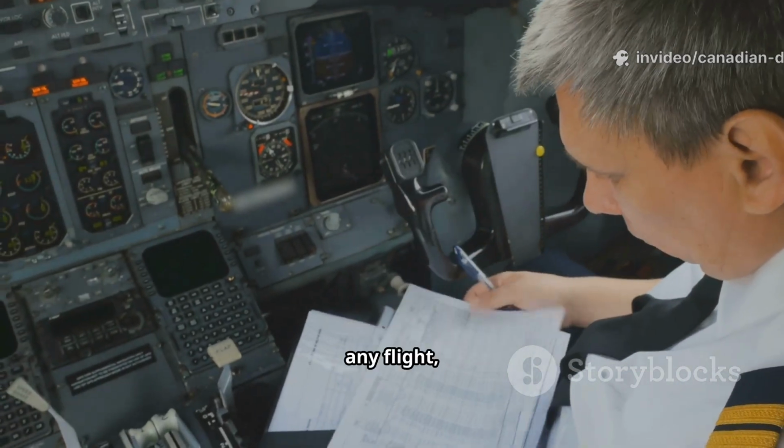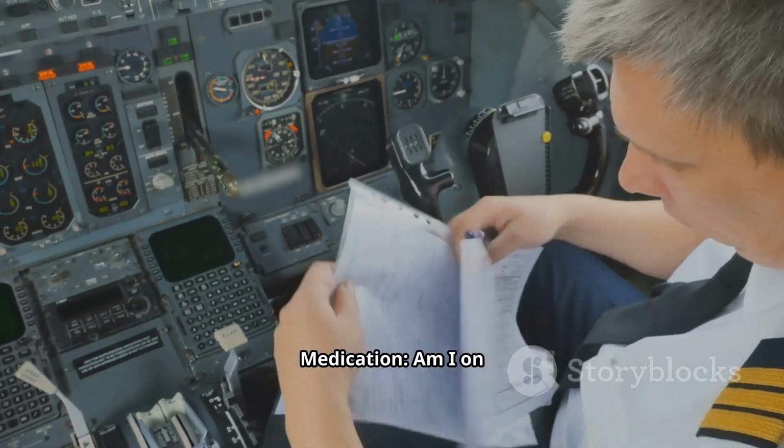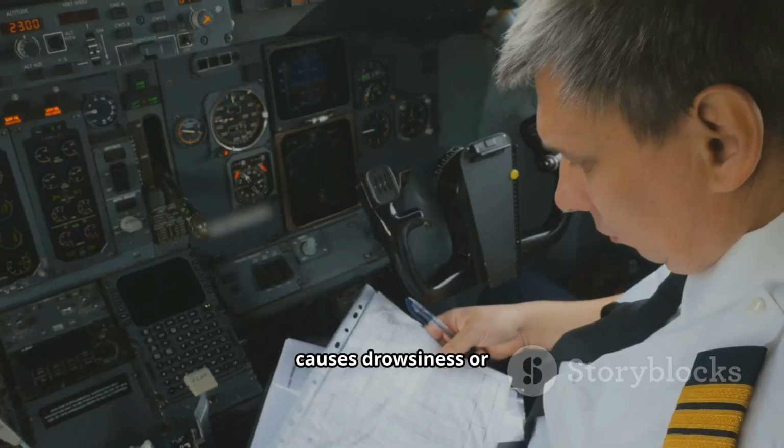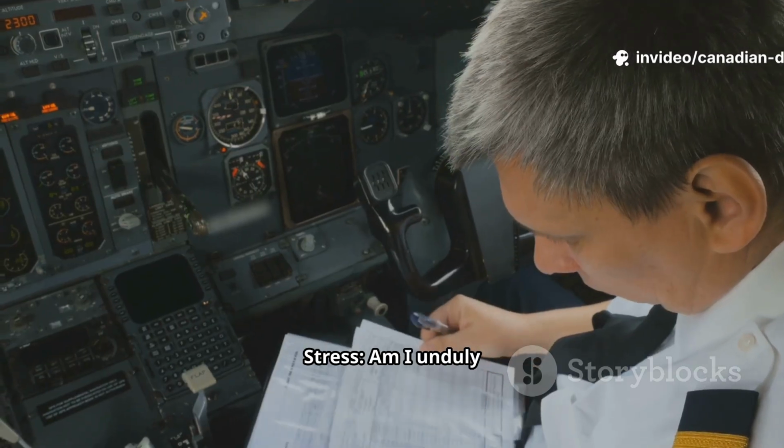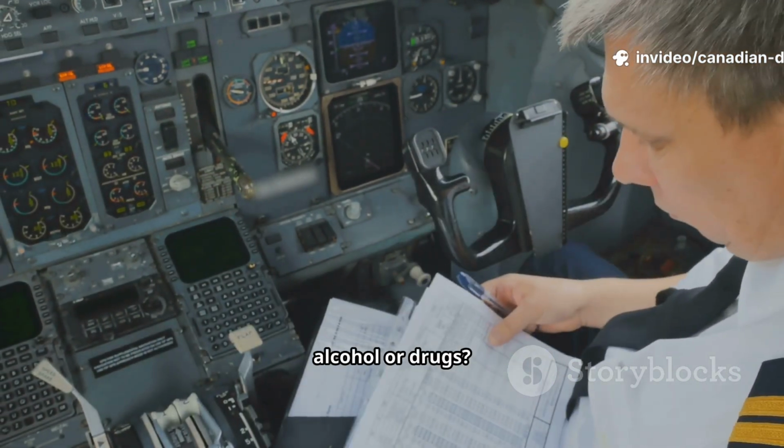The I'M SAFE checklist, a pilot self-check. Before any flight, ask yourself: Illness, am I feeling sick? Medication, am I on any medication that causes drowsiness or impairs judgment? Stress, am I unduly stressed or rushed? Alcohol, have I consumed alcohol or drugs?